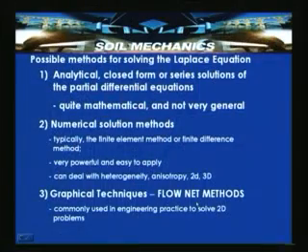So, the flow net methods can be applied for solving and computing the flow through a two dimensional plane, so that you will be able to compute the seepage or leakages occurring in all these two dimensional flow conditions. So, the solutions we are listing are analytical and closed form solutions or series solutions of the partial differential equations, numerical solution methods, or graphical techniques based on flow net methods, which are commonly used in engineering practice to solve two dimensional flow problems